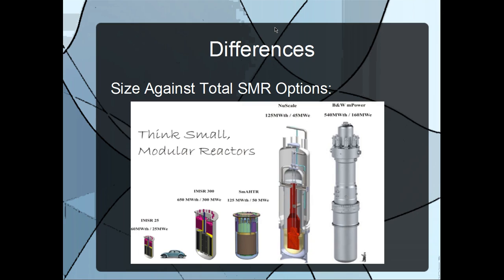The light water SMR designs are all based on concepts currently used in many commercial and military pressurized light water reactors. The major design difference, which has caused these reactors to stand out from the current global fleet and become a popular economic and energy discussion, are their much smaller thermal outputs and modular production and installation concepts. The size of these SMRs ranges from 45 megawatts of the NuScale power module, which can include up to 24 modules in one facility, to the 200 megawatt reactor design from Westinghouse.